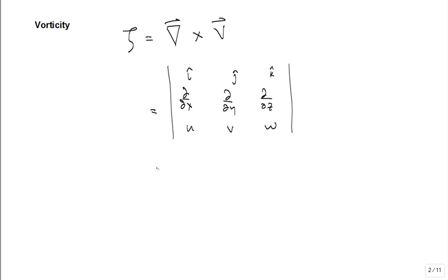And then how is the vorticity related to the rate of rotation, omega? This is a vector entity, omega. It's 1/2 the vorticity. So some textbooks will define the vorticity such that it does give you that rate of rotation. Some of them, well, you have to put a half factor in there. This textbook, I believe, has that half factor in there. Okay.